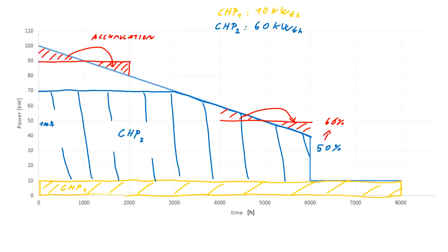So this is how the accumulation works, where the accumulation is only for 10 kilowatts of thermal output, and the storage capacity would however need to be determined from, let's say, daily or weekly diagram of thermal load. It cannot be determined from this summarizing diagram. And the last point would be the peaking boiler, which would need to cover the remaining 20 kilowatts.